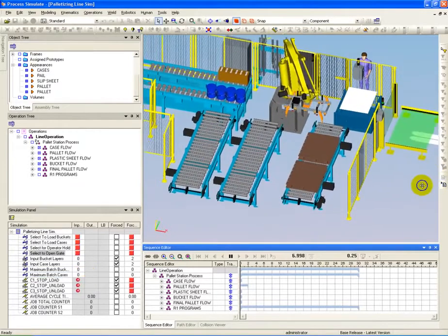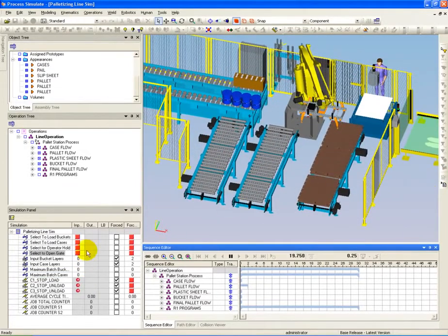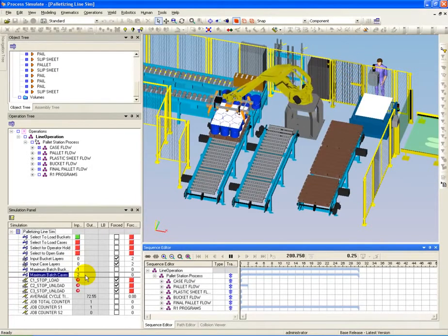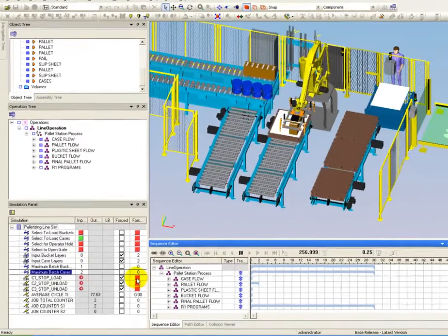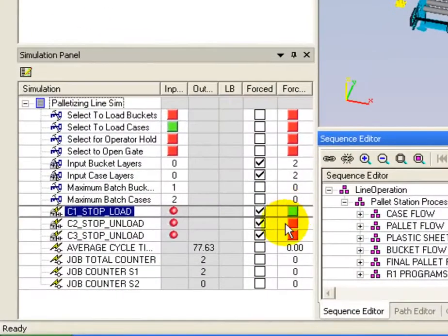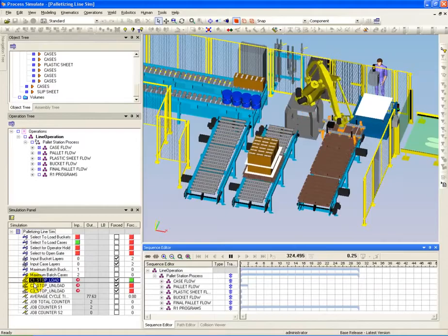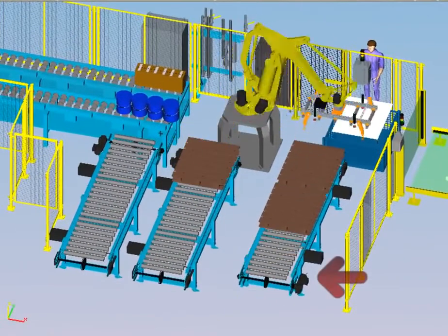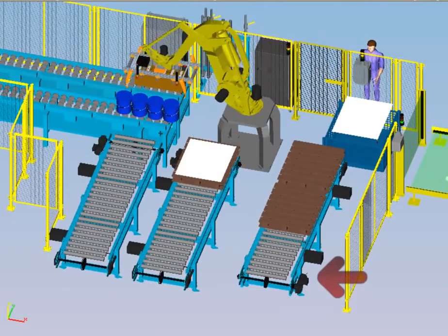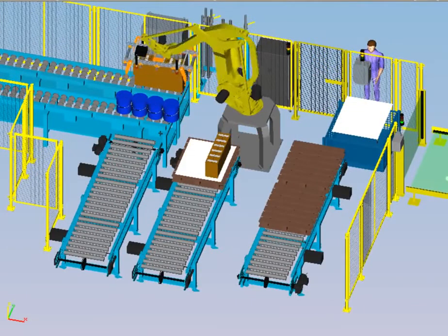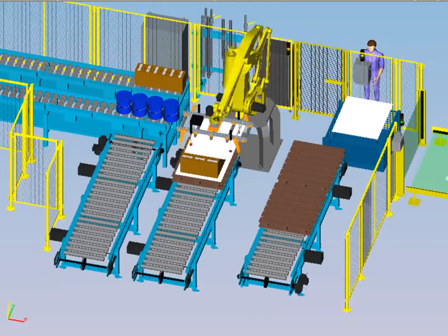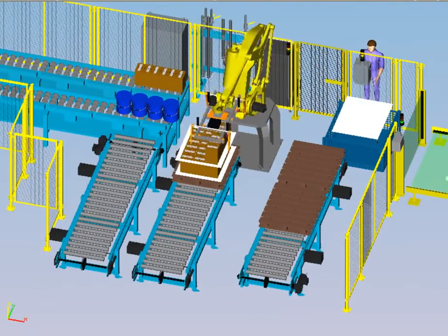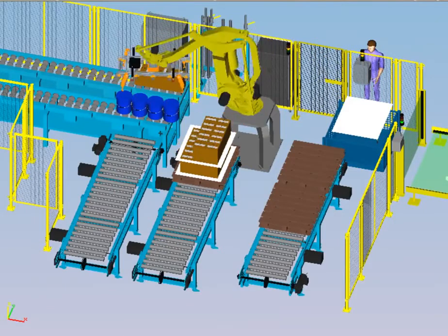Now let us test some fault conditions to check that some of the critical robot execution criteria are met. First, we'll test what happens if we starve the inbound conveyor that's feeding the pallets. You can see that now the conveyor has stopped loading new pallets into the system. This could be a common real-world scenario if the supply of new pallets is disrupted because of events outside of this scene.